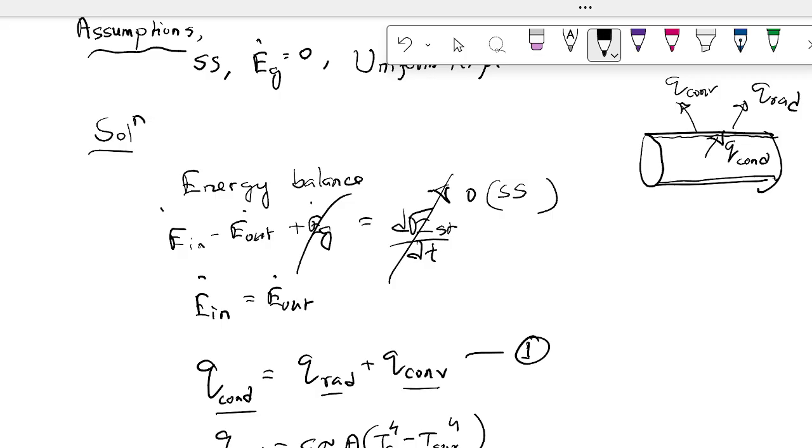Now here's one catch: the surface area. You want to calculate the surface area for the pipe. If you remember, the diameter of the pipe is D, and the surface area can be written as A. I'm sorry, I'm writing it on the side. Please don't get confused. This is for the surface area I'm doing here, right? So it is pi D L. Where do you get this equation for the surface area of a pipe? You know it from geometry, right? Pi D L. You know all those values, so let's just plug those in. D is 0.1 meter and L is 25 meter, the pipe length, and A is 7.85 meters squared.